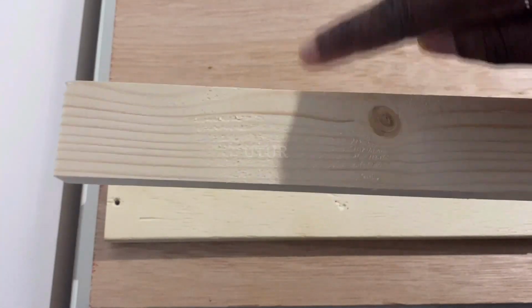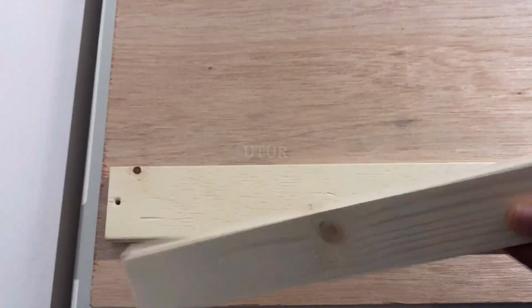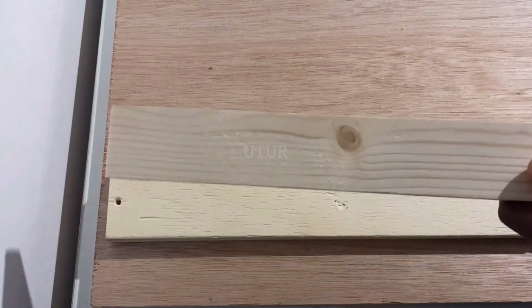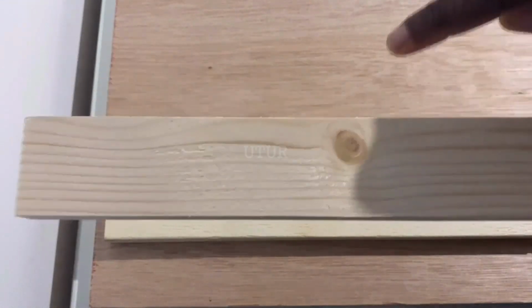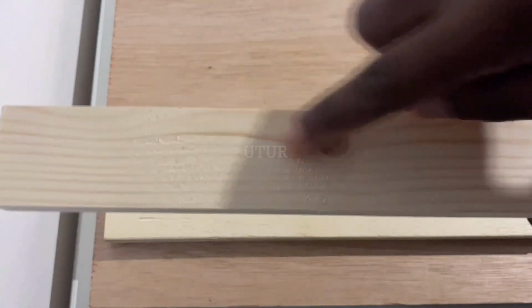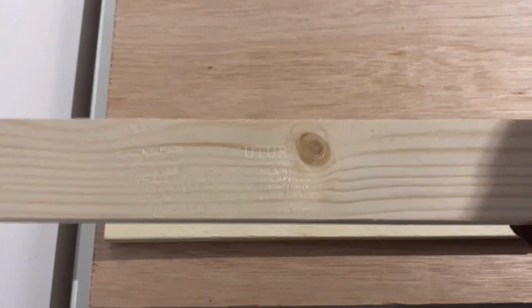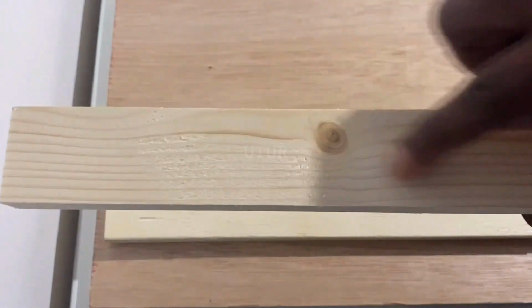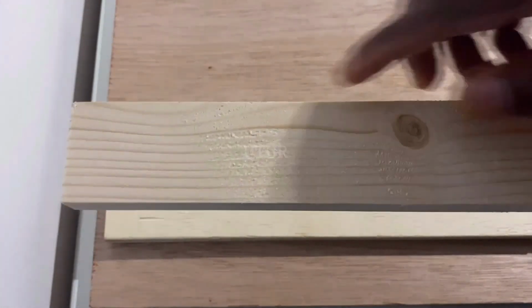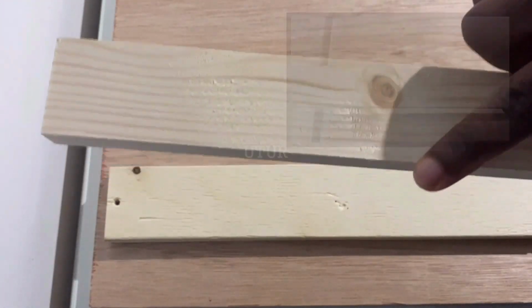If you cross-cut from the end grain with a ripping blade, you will only get tiny fibers off your wood. And that is because a dedicated ripping blade is not suited for cross-cutting. Do not use a rip blade to cut plywood, melamine or MDF. The quality of the cut will be poor with excessive tear out.